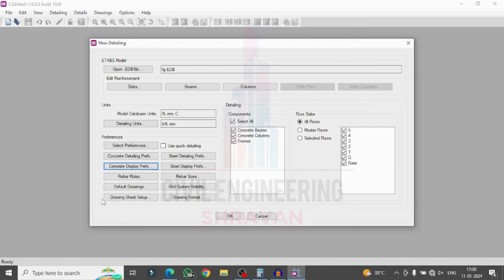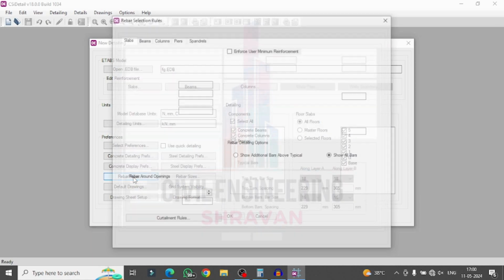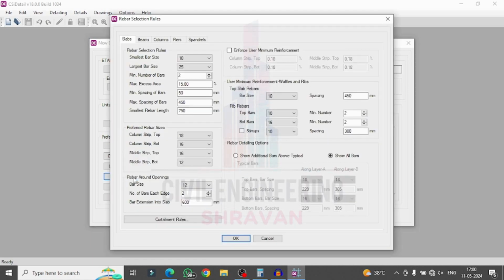If you want you can edit, but this is important related to rebar rules option. So here in this case we have to provide the minimum spacing as well as the maximum spacing for the structure. So for that I am selecting here slab. For the slab, the minimum spacing I require is approximately 120 mm. Here I am considering maximum spacing as 300 mm, according to considerations.